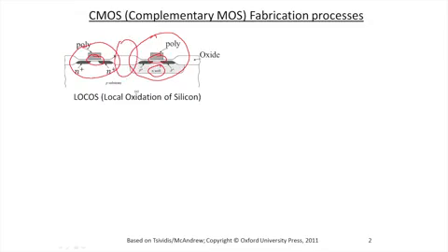And the reason for that is that if you happen to have other structures, for example, metal running across the chip and connecting one device to another, let's say if you had a metal over here, sufficiently positive potential on the metal could induce electrons below it, which can interfere with proper operation.